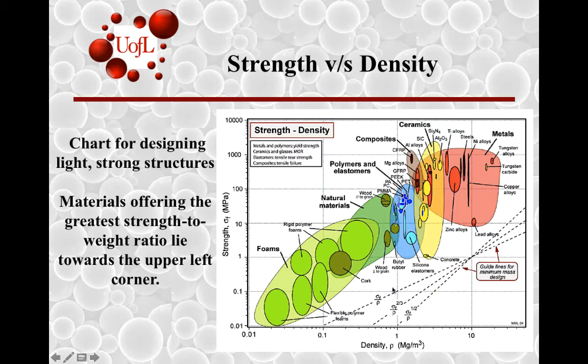You will also see that there are different kinds of slopes you can apply. In our particular case, we are just looking at the slope of 1. So anything as this gets maximized, if you draw a line parallel to this, you will be able to select, depending upon the yield sigma by rho metric based on L and F, you will see different options that are screened off below the line and different options that are compelling alternatives if they fall above the line.